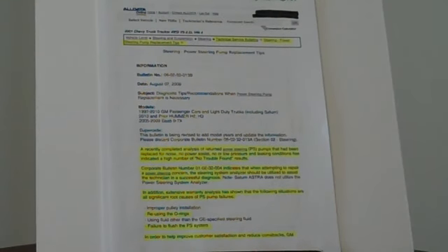The first TSB, power steering pump replacement tips, suggests the use of a power steering analyzer to detect different concerns with the system, including leaks, which has indicated a high number of no trouble found results. Also, the power steering system analyzer should be utilized to assist the technician in a successful diagnosis. The TSB also suggests other recommendations to help improve customer satisfaction and to reduce comebacks, such as bleeding the system. And finally, skipping steps may cost you time and trouble later.